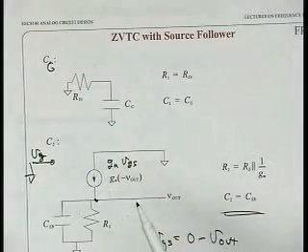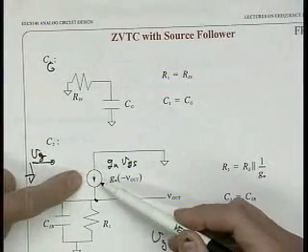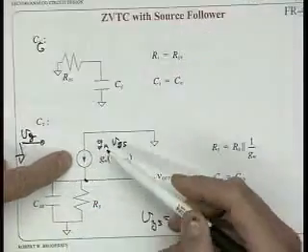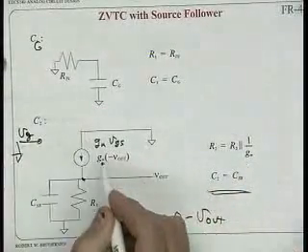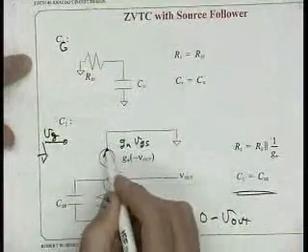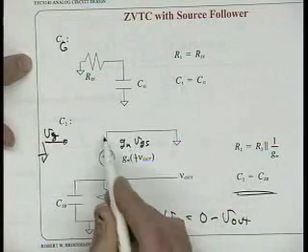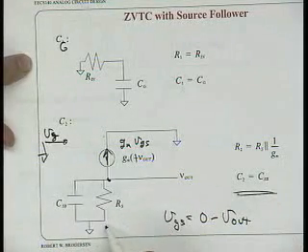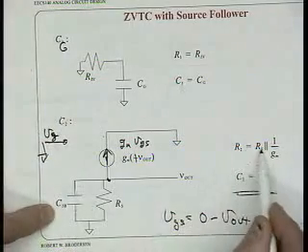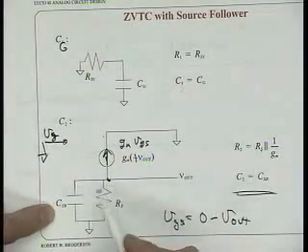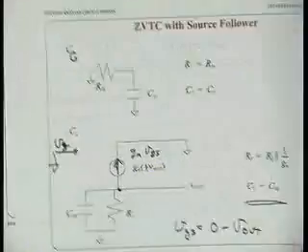And what's the answer to that one? We can do that right away. This is a dependent source dependent on the voltage across it. If we change the polarity of this, make it in this direction and get rid of that sign, this is just simply 1 over gm in parallel with RS. So the resistance of this is RS in parallel with 1 over gm. So that's 2 down.